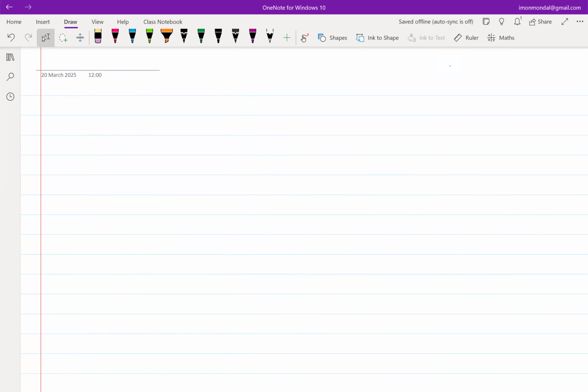These Y parameters or Z parameters are effective if you can short or open a particular port effectively. In principle, you'll never be able to short or open ideally. That is one problem, because even an ideal metal wire will have some inductance, and even an ideal open circuit, which probably terminates to something, will have some capacitance associated with it, which means you can neither effectively short nor effectively open anything.